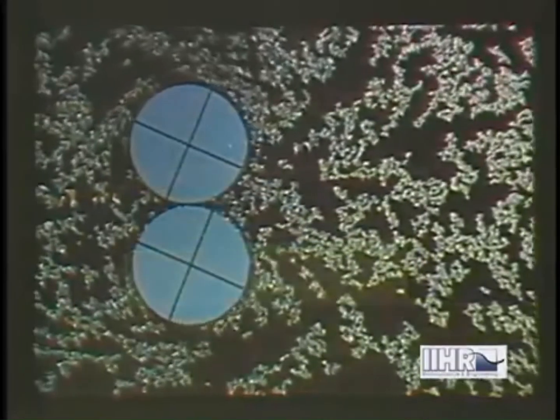Finally, it can lead to oscillation of the flow, with a corresponding pressure fluctuation, boundary vibration, noise generation, and perhaps even structural damage. Though separation is very essential in the operation of parachutes and baffles, it should in general be avoided by the control of the boundary layer or the pressure gradient, or of both together. If the boundary moves with the flow, for example, the retardation by shear is offset, and separation obviously is prevented.